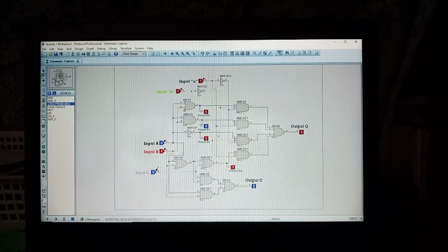Okay, so from there, we managed to verify that our 4 to 1 multiplexer is working, as is stage 1. The stage 1 and stage 2 are working accordingly, with the use of our logic probes to determine the input states and the output states. We've successfully identified stage 1 and stage 2, we've successfully created equivalents for them, and it's working as intended. Let me stop the simulation.